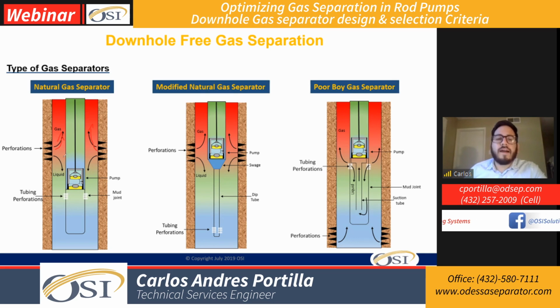If we have high fluid velocity, the liquid will start dragging all those gas bubbles directly into the pump intake. All right. So that's why we always recommend that when the gas problem is severe. So that's our natural gas separator.